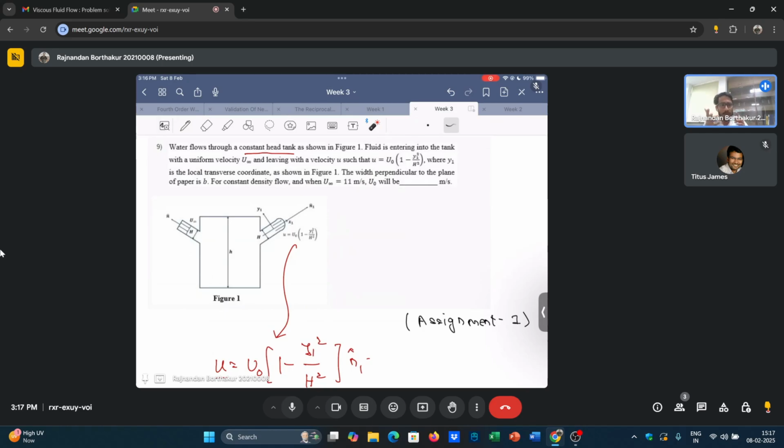There are a couple of things that you need to understand. First, in that problem, there is a net inflow of the fluid, and since the fluid cannot go out, and we assume there is no spillage, the height of the tank would rise with time, which means that problem was an unsteady problem. On the contrary, in this problem, the head of the tank is constant, meaning that this h is not a function of time.